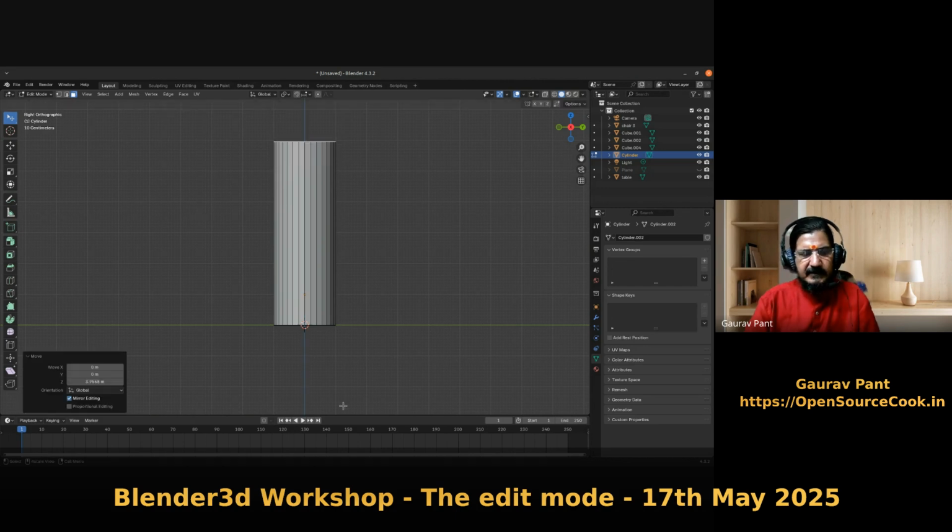Okay. Now, dependent upon the kind of shape that you want, we will run the loop cuts over here. Fine. Increase the number of loop cuts, let's say 3. Now you have to think accordingly what you want to do. I want to do some separate operations on separate areas of this bottle. So once this is subdivided, now I will do the loop cuts over here and increase the loop cuts. So you will notice that the loop cuts that are increased over here are only in this specific area. Fine. Now I'm going to put some loop cuts over here.